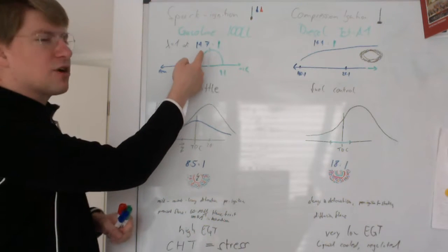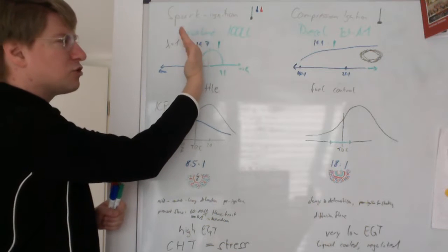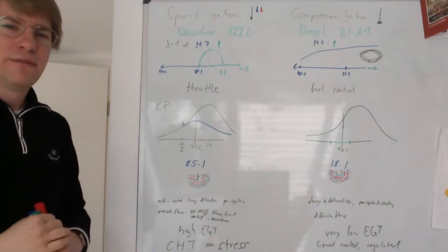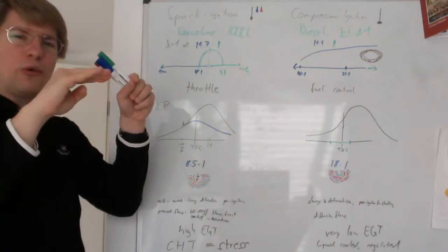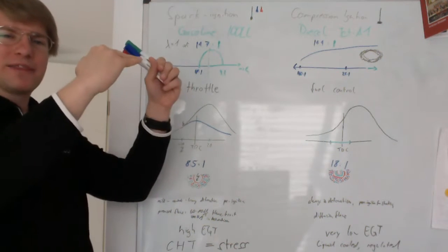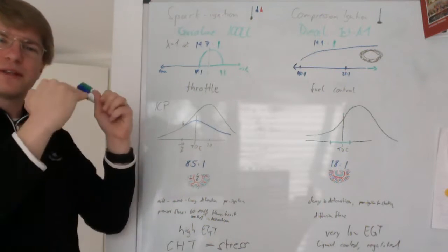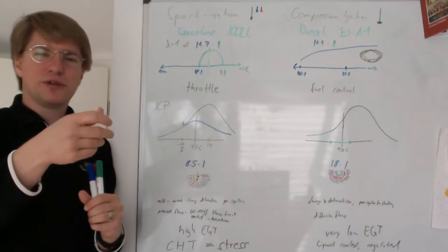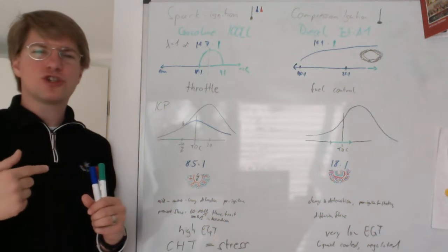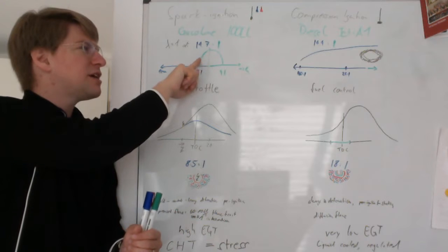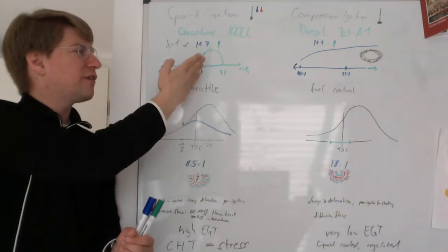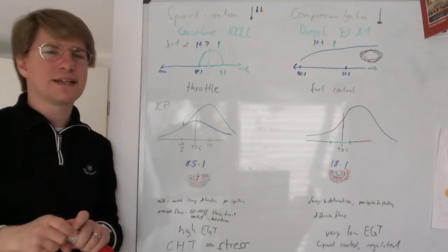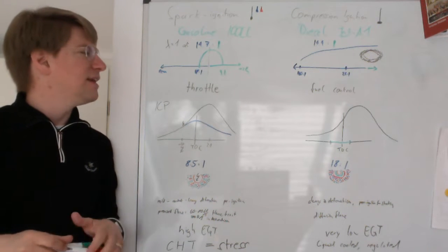All right, so for good economy, we want to be a little bit more on the lean side of this maximum line, which lowers the power a little bit, but the drop in fuel flow is bigger than the drop in power, so our efficiency is better. If we continued to pull the mixture out even from there, you see there's a very sharp drop in the curve on the lean side, and at about 18:1, the engine quits running. It's impossible to burn this lean of a mixture.